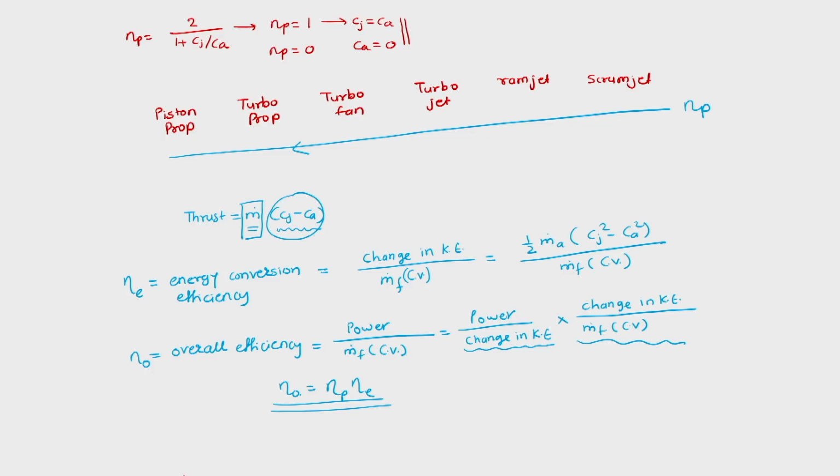So this is the formula for overall efficiency of a power plant. So these are the aspects that define the comparison, how to quantify and how to compare between two power plants. There is one more thing which we can use for comparison, which is the specific fuel consumption. Specific fuel consumption is defined as mass flow rate of fuel divided by thrust. So here we can divide by mass flow rate of air in both the cases. So this becomes f, which is fuel air ratio, and then this becomes specific thrust. So this is how we have specific fuel consumption defined.